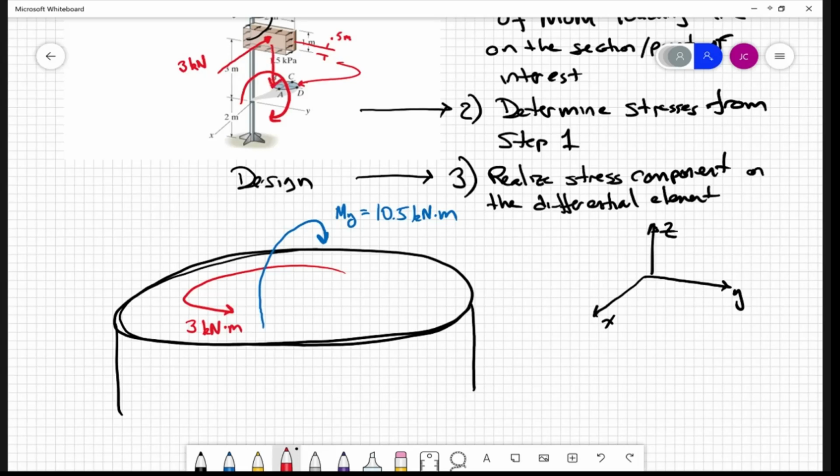Imagine it's 100 kilograms. So that would be roughly 1,000 newtons of force acting down, assuming gravity is 10 meters per second squared. Okay, a downforce: what types of loading would that add onto this cross section?